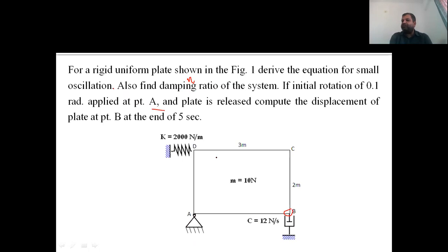It is the same as what we have done in the previous example. But in this case also, in the particular vibration case, first we need to establish the equation of motion. From this, we need to ascertain in which particular vibration this has been rotating. Once it is known to us, then we need to find the value of frequency corresponding to the natural frequency and the damped frequency, and then we will put it into the general equation of displacement.